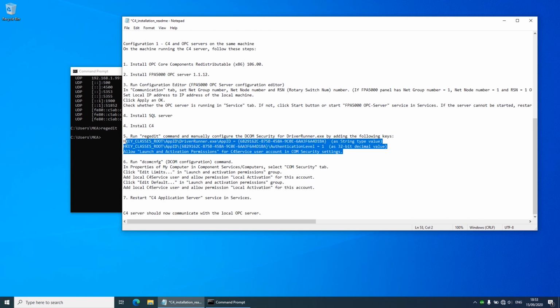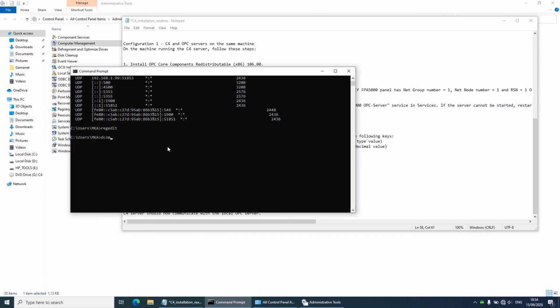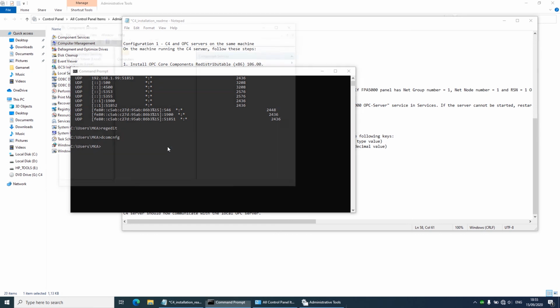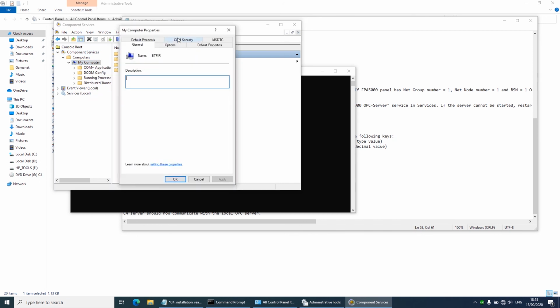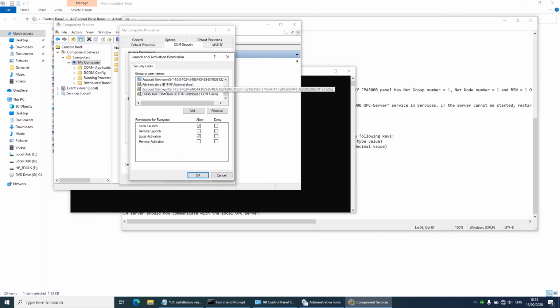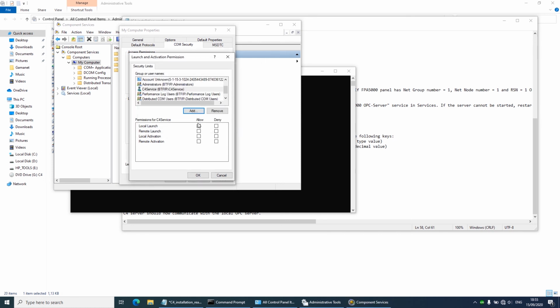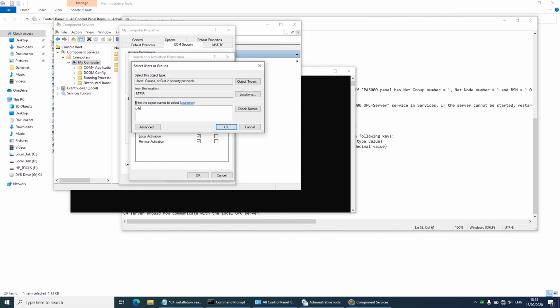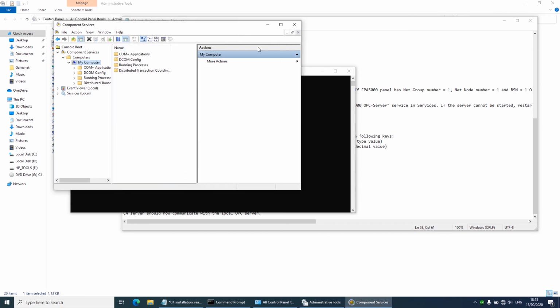And then we finish this step, and the last step is to set up the DCOM. We need to go to the DCOM setup, DCOM config. Okay, then in Component Services and Computers, My Computer, we right click and go into the properties and go to the COM Security setup. Only needs to set up this, but the most important thing is to add the user which was created by C4 service. Check name, it should be there. If it's not, that means installation is wrong. Usually it's there, and edit both of them and also add the user here. C4 service. Check them again and click OK. Check all of them and apply OK, and then we're done.